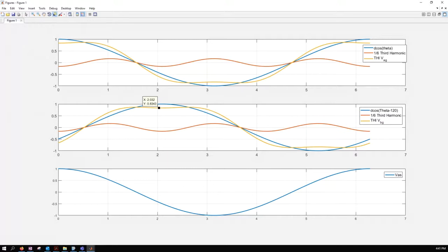More than half your DC bus voltage. If you remember from our previous case, we were limited to half VDC, right? But in this case, we have more room. See, this is our D, the total modulation, right? We have room here to increase our D so that we can get the phase voltage to increase slightly. So this means just by adding the third harmonic component, you can supply a little bit more voltage. I believe it's 15% more voltage than the regular sine triangle modulation based case.